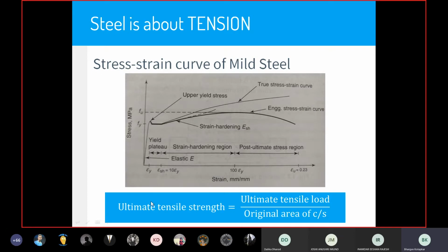So the load that you are talking about might be somewhere here. The load might induce a stress that is somewhere here. But I will design for a stress when it is maximum loaded. It is the worst condition. So every structure and every member is designed for the worst condition. It is designed for an earthquake. Tall buildings are designed for the worst wind.